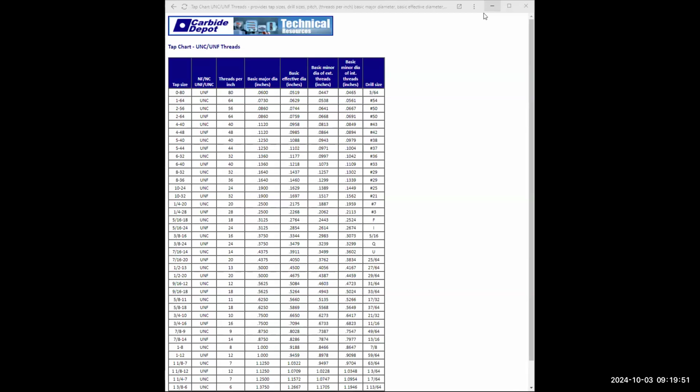enter. Click on the text you want to modify. Well, here we're going to type in SF, which means spot face, space, percent, C, space, 1.00, click, enter. Wow, we're almost done with this, believe it or not. We're going to try to get done by 9:40.